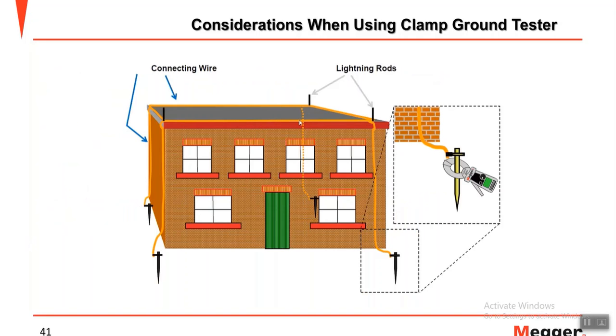So as long as you put the clamp on the electrode under test that goes directly to the soil, you will get a correct result, close to the actual measurement. But the problem is if you put this clamp on another electrode that is not connected directly to the soil. An example here, maybe a loop: you want to measure this ground, but actually this loop is lower than the other loop.